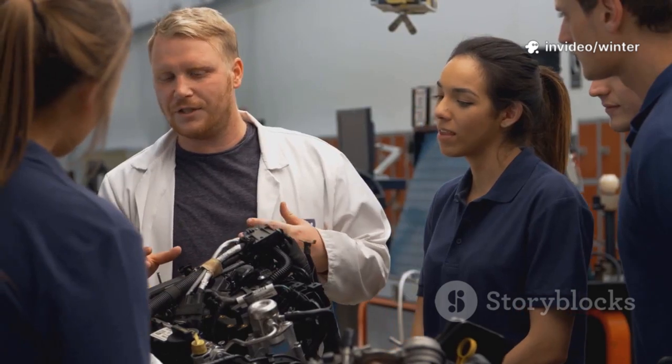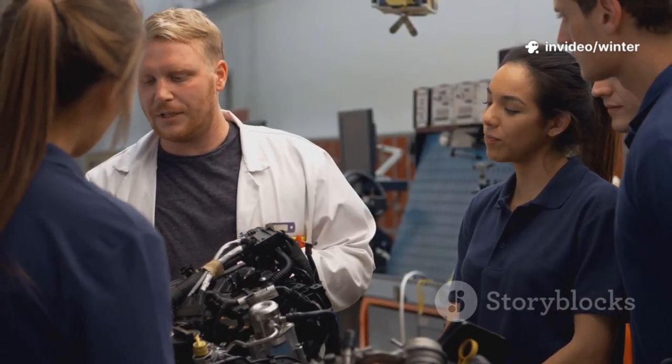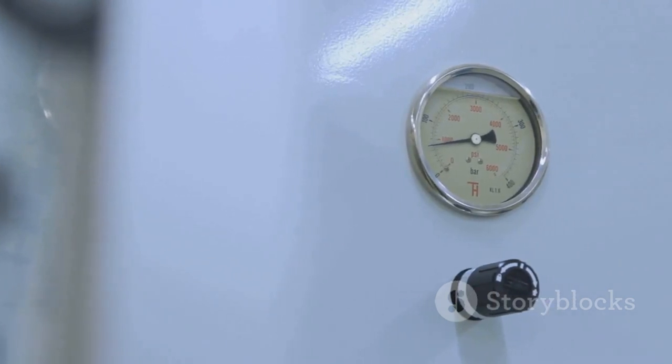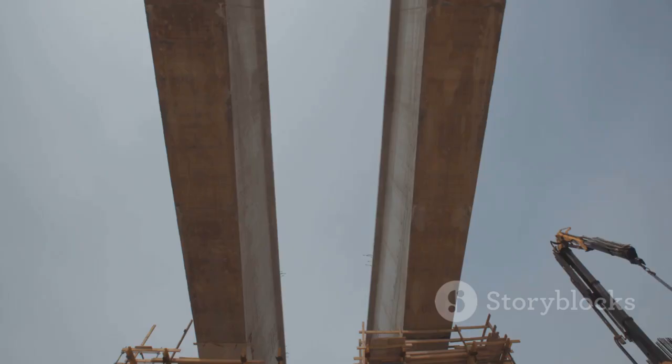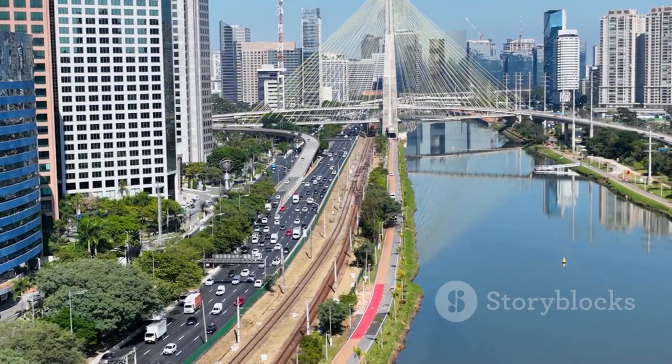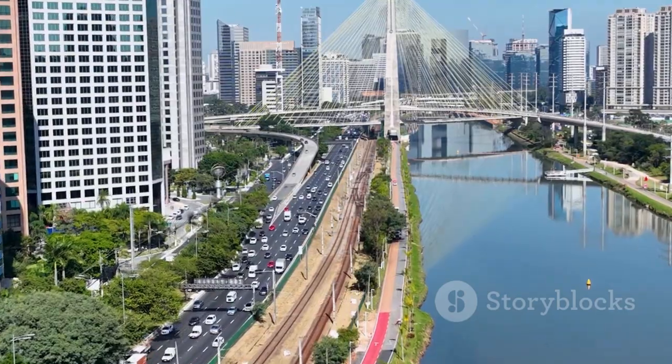Stress is internal force per area. Strain is the proportional deformation. Stress is measured in pascals. Strain is a ratio. Understanding this relationship is essential for safe bridges, buildings, and everything in between. That's the science behind the structures that shape our world.